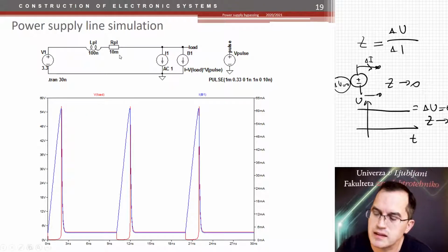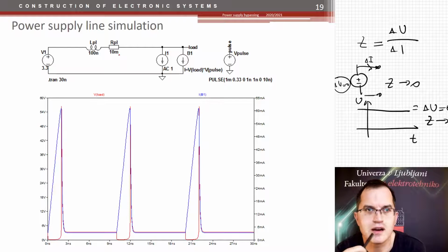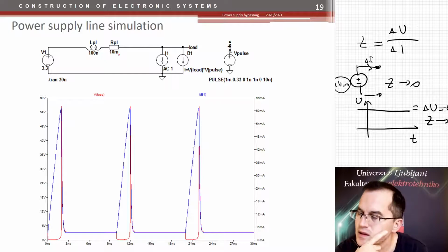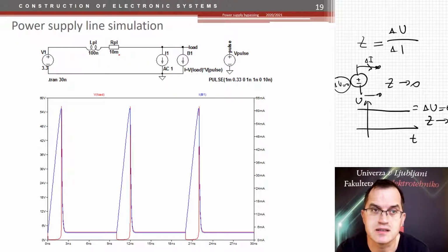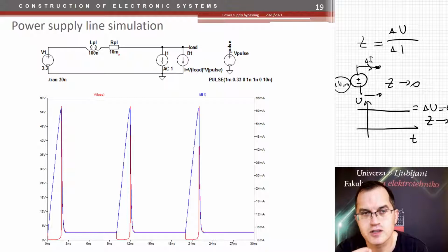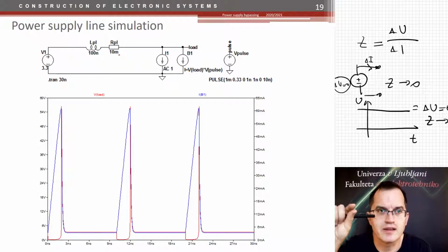And that behavior of a coil is very well used in petrol engine cars when they are generating sparks for the spark gaps to ignite the engine. And yeah, there the coils are very useful. Here we don't need them, we don't want them, but they are there in every circuit. So this is totally useless if you have a voltage power supply and a 10 centimeter track and the microcontroller taking 1 amp from the power supply. It would be disastrous. So we need to do something.